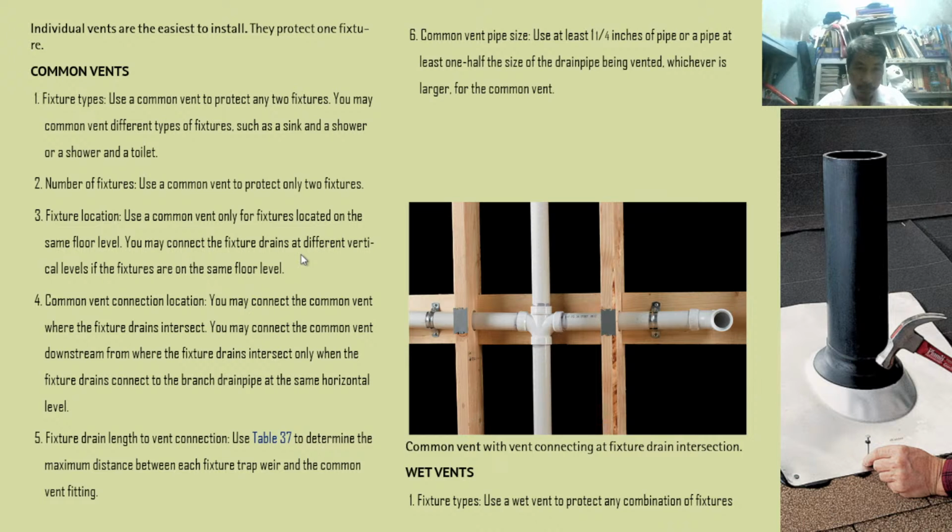You can connect fixture drains at different vertical levels. They have different levels, but they are on the same floor. Okay? You cannot do it connecting the vent with the common vent from one floor to another.